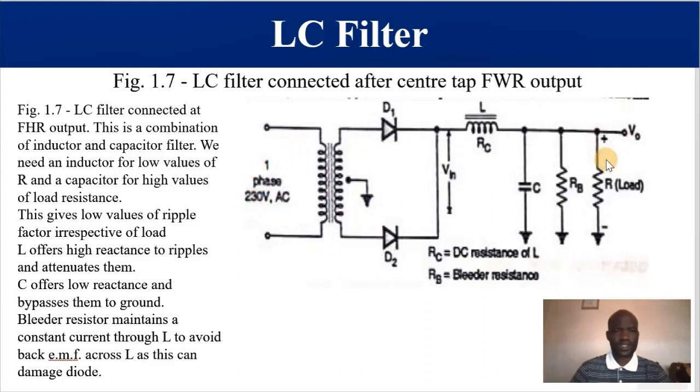So we are saying an LC filter is connected at the output of the full wave rectifier, and this is a combination of an inductor and a capacitor. We need an inductor for low values of load resistance, and a capacitor for high values of load resistance. There is a phrase in one of our previous slides which talks of problematic AC components. These are going to escape the opposition of the inductor, but they are going to be dealt with by this capacitor.